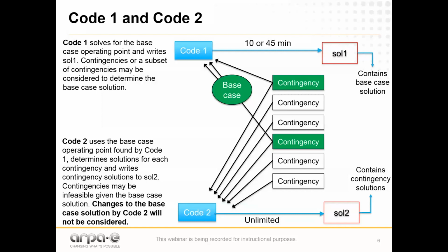So by soft constraints, we are basically saying, even though the true line limit of this transmission line is 500 megawatts or 500 MVA, if you end up violating it with your power flow solution and you get 510, you're going to get a penalty on that 10 megawatts or 10 MVA, okay? That's basically then a soft constraint. We are allowing you to violate it from the true limit, but then the violation just gets penalized. That's an addition of a slack variable into the constraint and the addition of the slack variable into the objective. And then the hard constraints are basically everything else, where we're forcing you to abide by them fully.